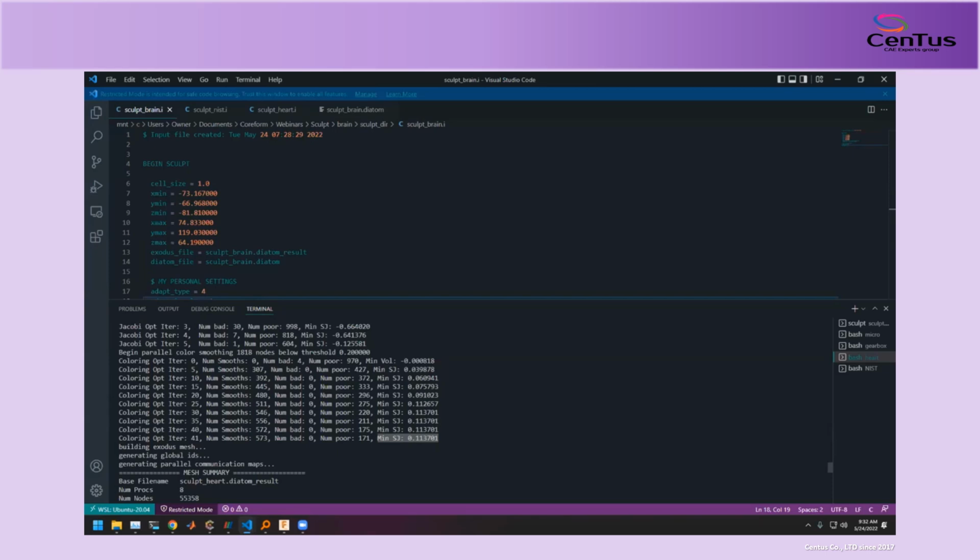But if you do have cases with those large differences, it may occur that Sculpt might miss those small features that branch off. If that's the case, then I would recommend using a denser or finer initial mesh. But that is a good general application for Sculpt, these biological or organic shapes.